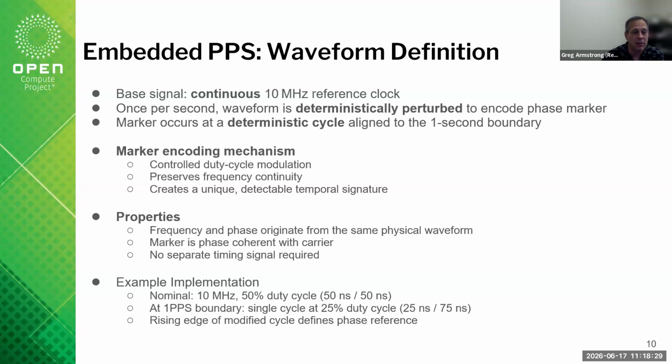That 10 megahertz clock, even with a modulated signal or even multiple modulated pulses, really is not going to have an impact on the ability of a phase lock loop to lock to that clock and resynthesize higher frequency clocks, which I've talked about in other discussions, the concept of a phase lock loop and what it does. Typically, the phase lock loop is looking at the rising edge. It really doesn't care about the falling edge. It's not a necessary mechanism when you're multiplying up a clock or synchronizing a clock using that reference.